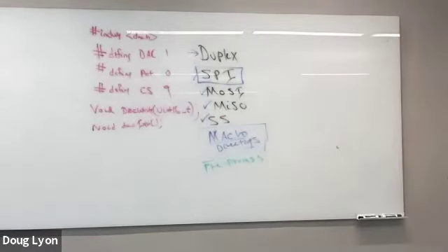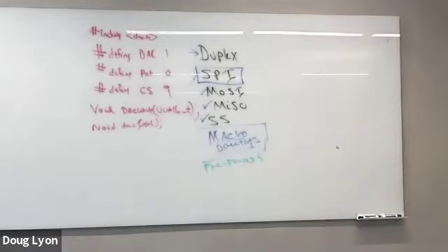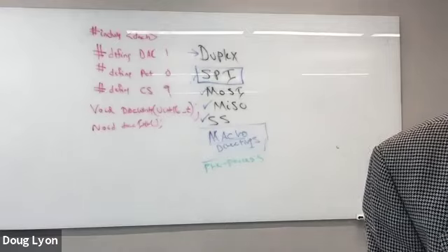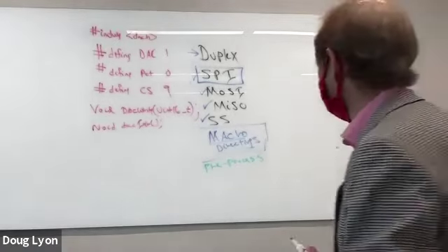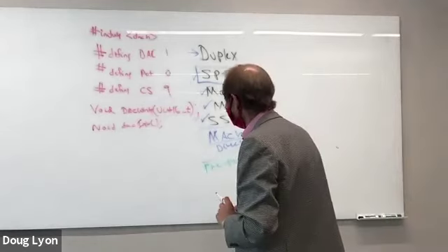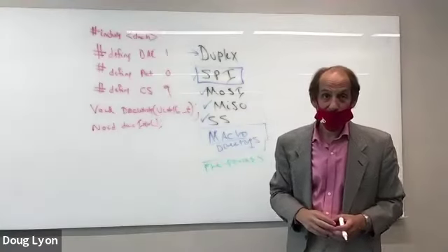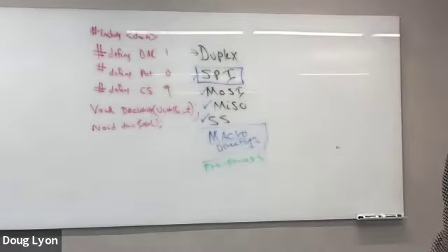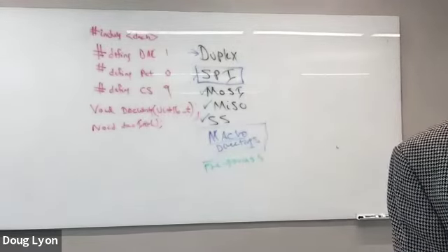So where is the chip select? This is the question known as question 14, homework number 3. Where is the chip select in this code? Pin 9. Yes, pin 9. It's clear, right? And that is where you have to wire the DAC. If you were to overwrite the chip select and change it, you have to change where the DAC is wired.